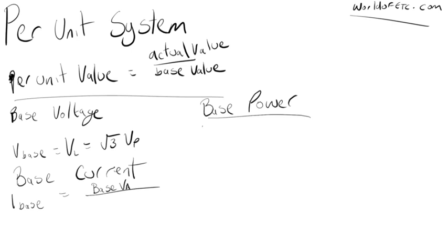Say you have a system with 5 transformers rated at 10 MVA, and then you have a 20 MVA one, you would convert the 20 MVA into a 10 MVA base to just keep it common. You'll run through it in a sec.